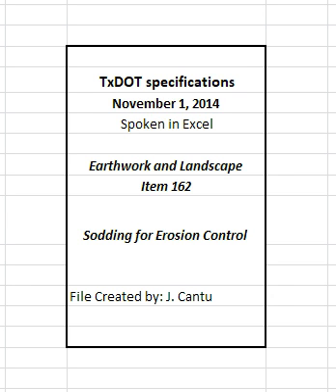3.1 Sodding types. 3.1.1 Spot sodding. Use only Bermuda grass sod. Create furrows parallel to the roadway, approximately 5 inches deep and on 18 inches centers. Sod a continuous row not less than 3 inches wide in the 2 furrows adjacent to the roadway. Place 3 inches squares of sod on 15 inches centers in the remaining furrows.